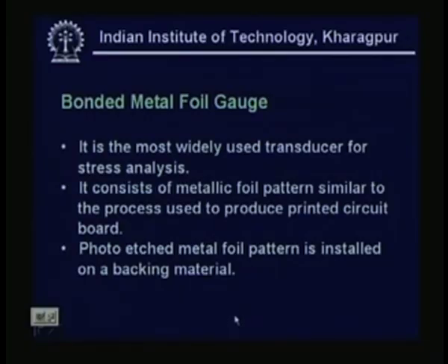So, the bonded metal foil gauge, as I told you earlier, is the most widely used transducer for stress analysis. It consists of a metallic foil pattern, similar to the process used to produce a printed circuit board. As you know, the printed circuit board,